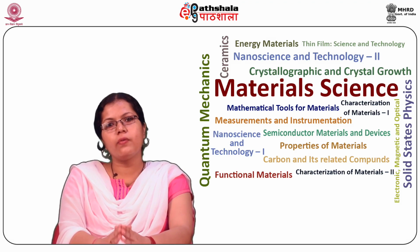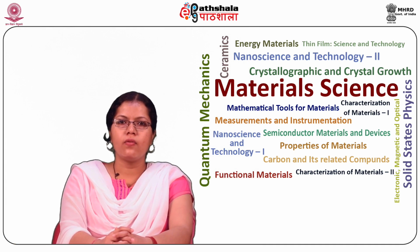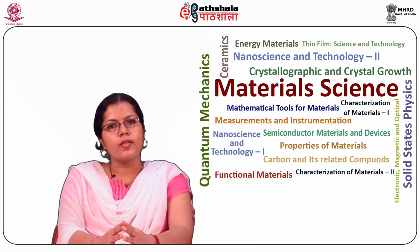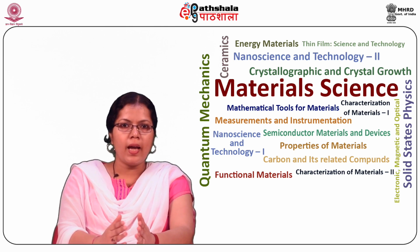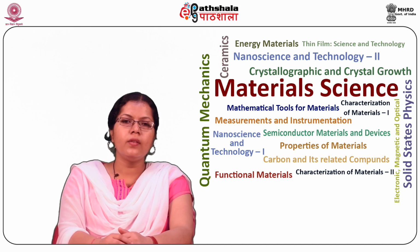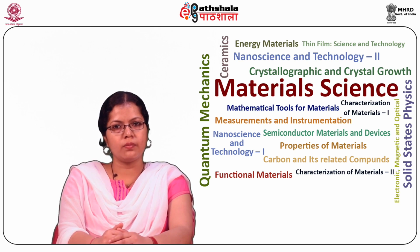It consists of two coils which are connected in different circuits for measurement of power. The fixed coils or field coils are connected in series with the load and so carry the current in the circuit. The fixed coils therefore form the current coil of the wattmeter.